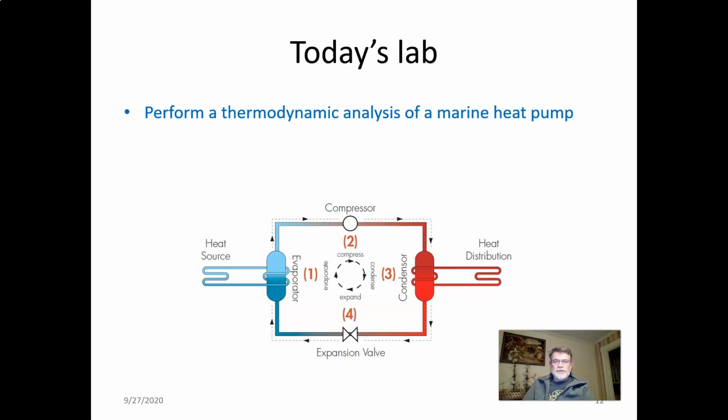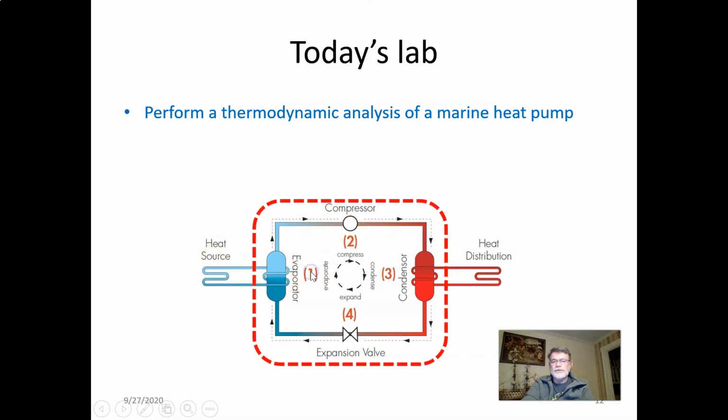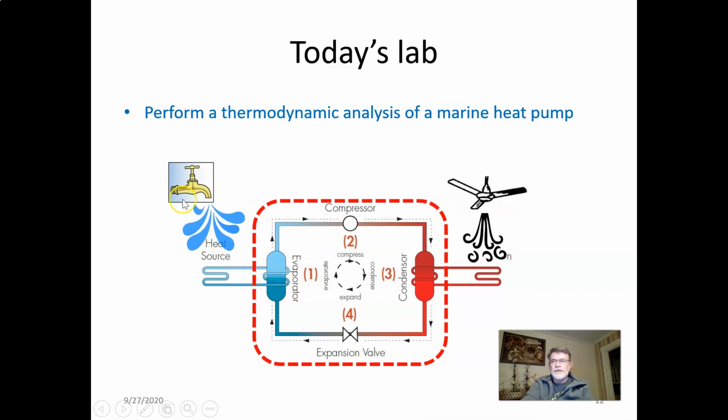It works according to that principle, and it utilizes R22 refrigerant, Freon. During the heating operation, the R22 absorbs thermal energy from a heat source, which is a 55 gallon insulated tank that you will see in the lab.